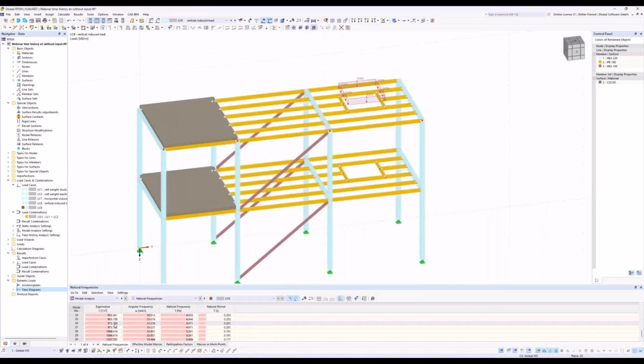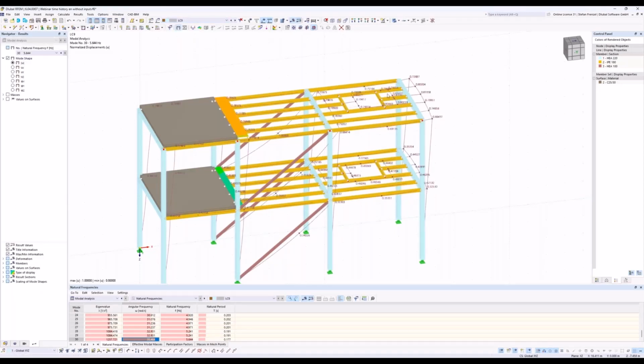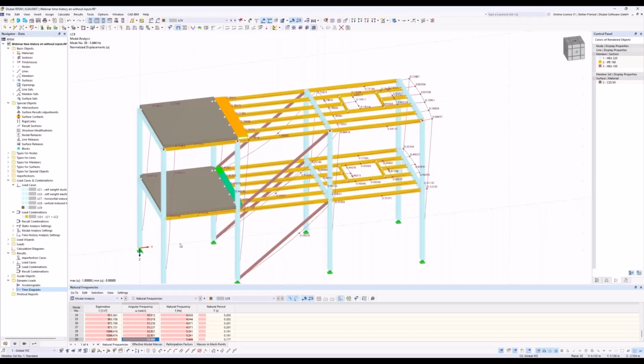In the next step, I want to show you that we have an angular frequency of 35.4, which is near 35.2. That means I could get a resonance in the whole calculation, because the horizontal part is my horizontal load. If I look at this eigenvalue 35.2 in load case number 9, I see a deflection in the x direction. So you have to be careful, as there could be a resonance in the structure. With this knowledge, we go to the time history analysis, hoping to see the resonance in the structure. Therefore, we create a new load combination.